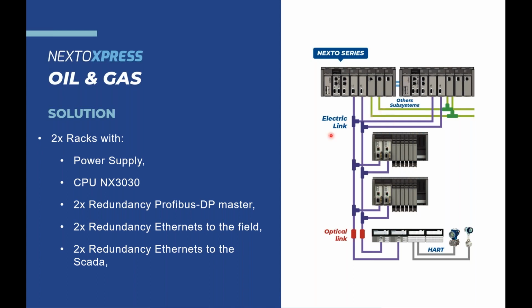the process. So in the first scenario, where we have one inactive, let's suppose that we have here a wire problem, and then you lose communication with this Profibus head. All the system will shift the communication to network B, so then we'll be able to communicate with this other module and keep control of this remote. We will have this over here coming here and control of this remote, and the same down there with the old device. But let's say that we have a simple fail.